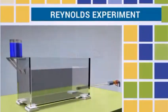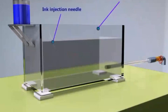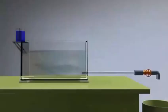Reynolds experiment. This section will attempt to illustrate Reynolds experiment. Have a look at the setup that is required for this experiment. A water tank is installed with a see-through, that is a transparent plastic or glass, flow pipe at its bottom. The flow of water through the pipe is controlled by a tap at the output side. Lastly, an ink injector is positioned at the input side of the pipe.